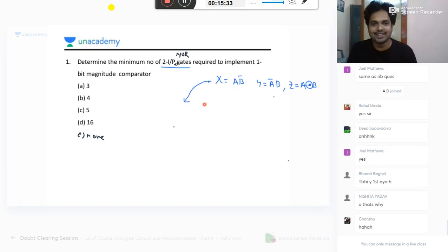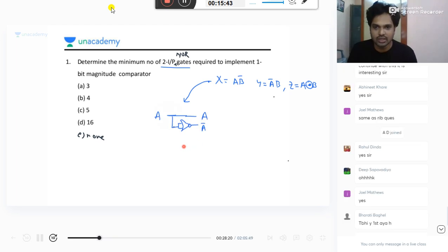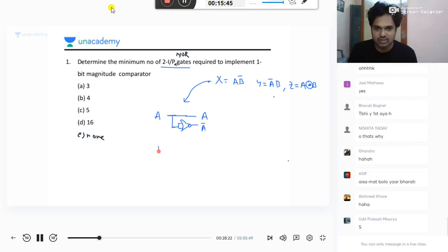Decoder, one of the important applications is memory addressing. We will use it to select one memory device. Memory blocks are there. Okay, you say 3 to 8. You give an address, one particular 8 KB is there. 1 KB, 8 blocks are there. Based on the address, it will select one block at a time.